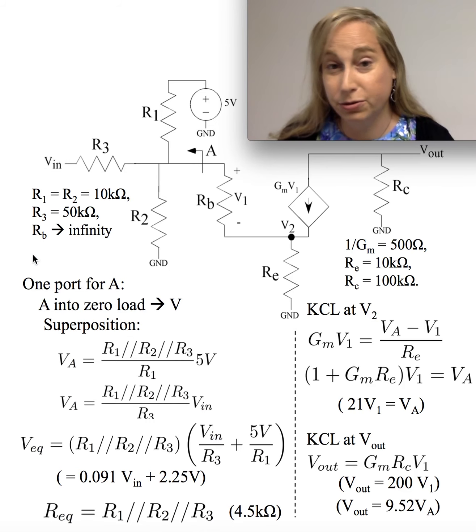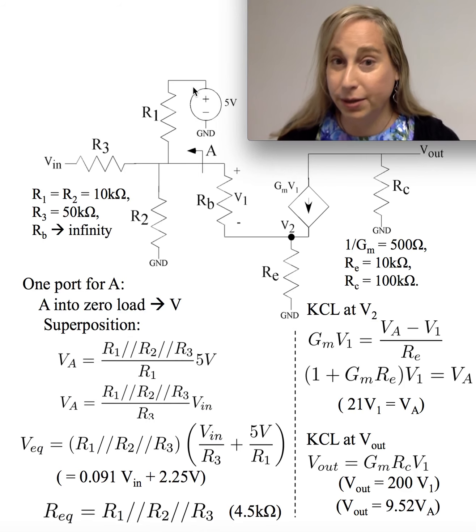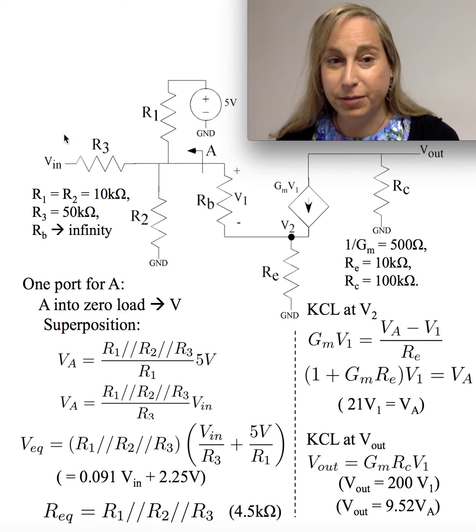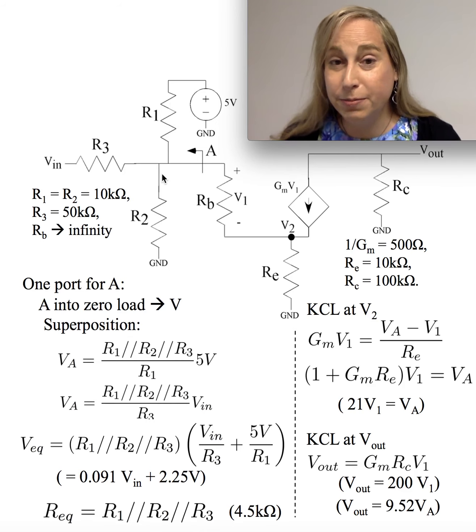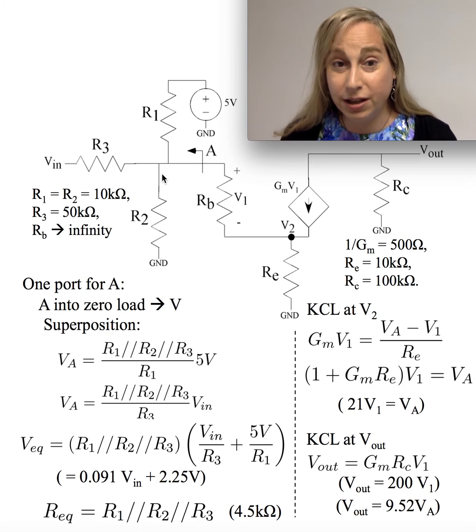So you can imagine it being drawn as a voltage source, much like I drew the second one, which is 5 volts. And you think, okay, so either way that would have worked. Often we'll think about inputs like this. And then I have something sitting at 5 volts here, so 2 voltage sources and 3 resistors. Now I know I should be able to combine all that into a single voltage source and a single resistor, right? This is the theory around one-port networks, and we're talking about Thevenin and Norton equivalence and so forth. So you begin to say, well, how would I solve it?